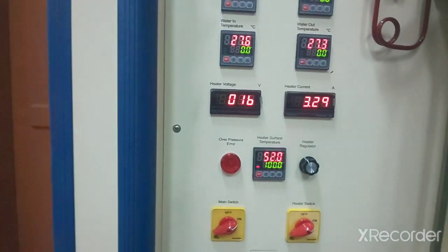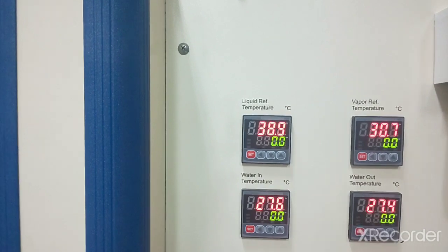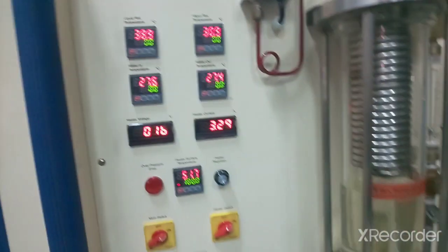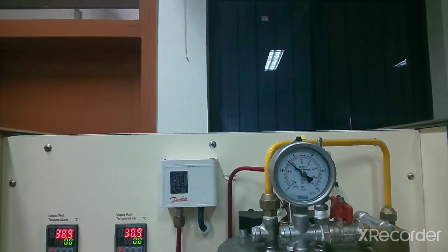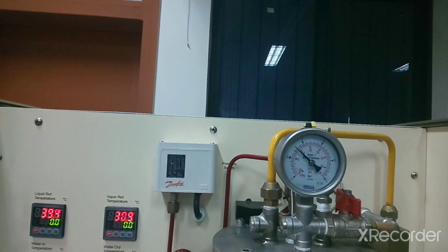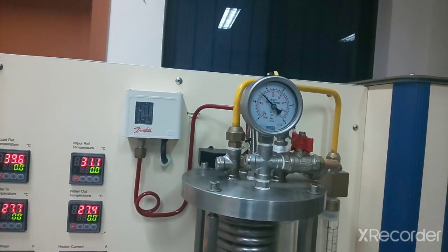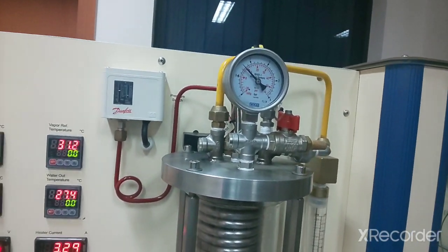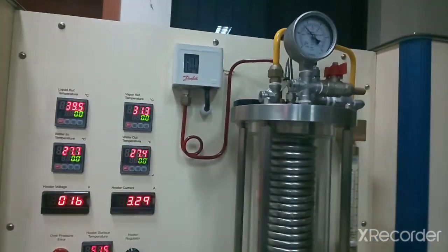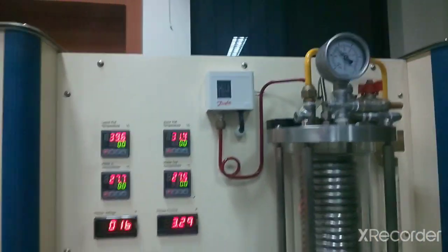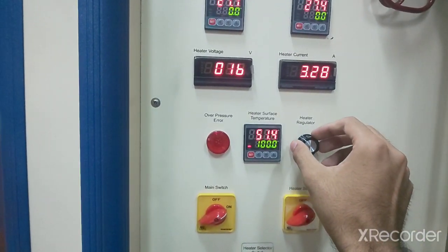Right now you guys might be wondering why the temperature of the fluid is going above the boiling point. Yes, it is a closed cylinder. The pressure inside it is increasing as well. So you guys can note the value of pressure that is also going up. If you want to keep the pressure constant, you will have to use the water inlet, which I am not using right now because I am only demonstrating. We are not going to take any readings. Right now the temperature is dropping, but it is not that fast.